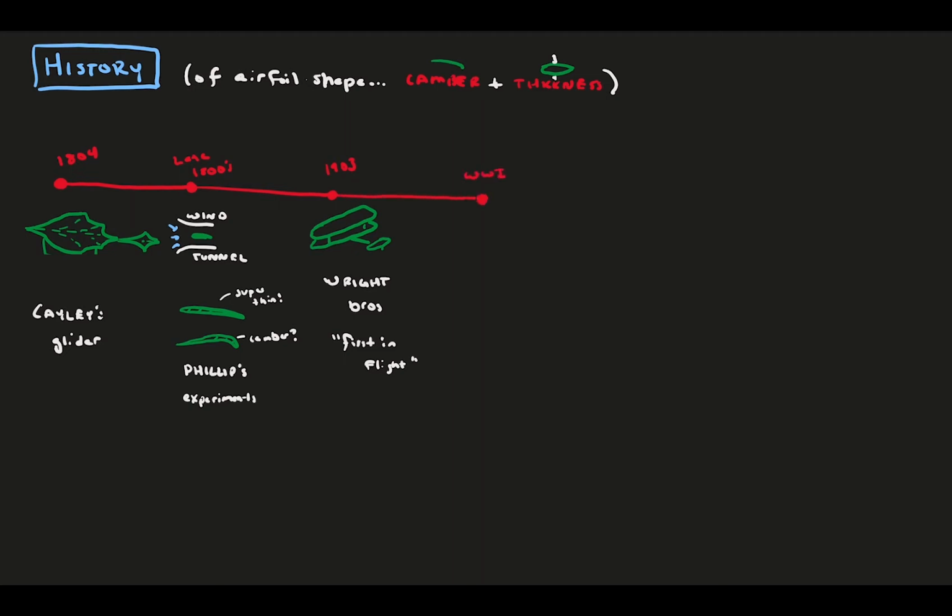World War I was very influential to aircraft development and acted as a catalyst for engineering design. Three of the most common airfoils you would have found early in World War I were the Eiffel 14, the RAF-14, and the Albatross, from France, Britain, and Germany respectively. All were incredibly thin airfoils.